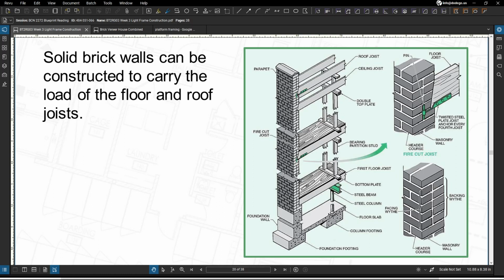You know, this is a cut on an angle that we see at the top right. Fire cut. This fire cut is used to rest in the brick wall. So in the event of a severe fire, the burnt out joist drops without pushing the brick firewall outward. A square cut joist end would exert a prying action, forcing that wall to fall.